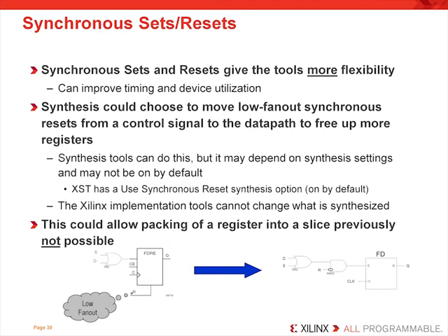Another big reason to use synchronous resets is that synthesis and place and route tools are moving towards selectively demoting a synchronous reset from the control port to a LUT input. This will improve your system timing and device utilization. Now, this is advantageous because less timing critical and low fan-out resets can save the reset port for other functionality. This would also allow the mapper to group unrelated logic into the same slice and improve device utilization and speed.